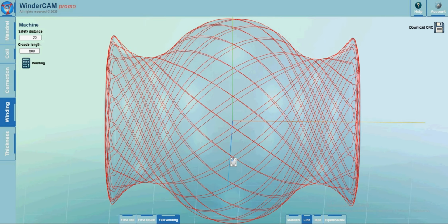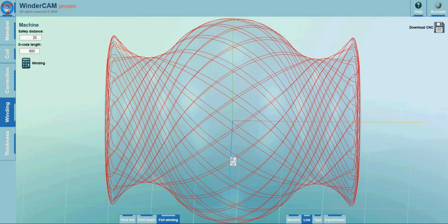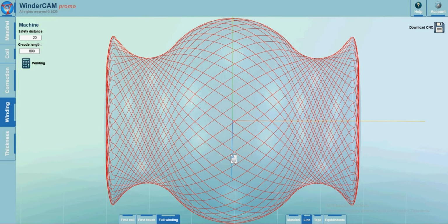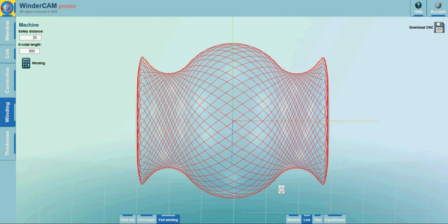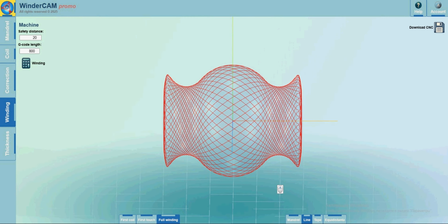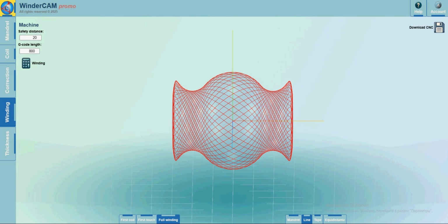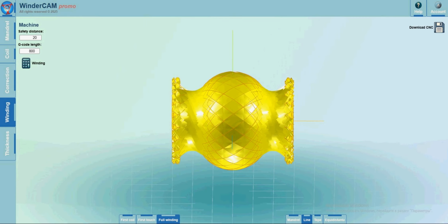Why does this happen? The reason is the simplified bending model. The current algorithm does not account for tape bending in two planes simultaneously. When the tape is wide and the surface curvature changes rapidly, as it does on the corrugation crests, the program can't accurately predict how the tape will conform. So it creates these visual artifacts.